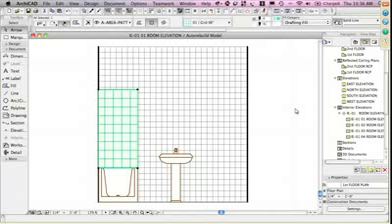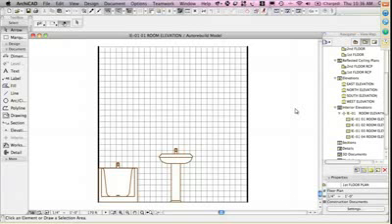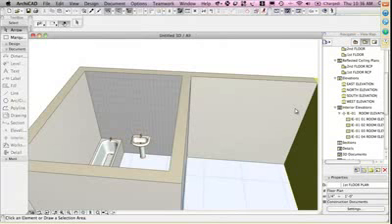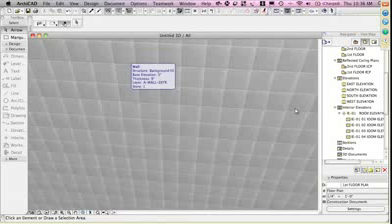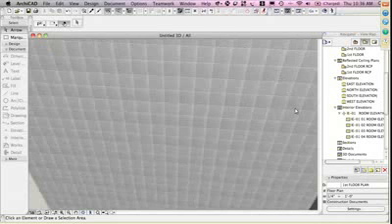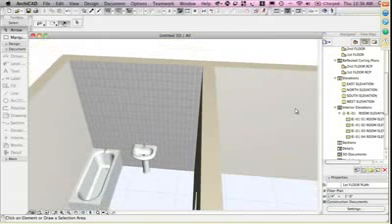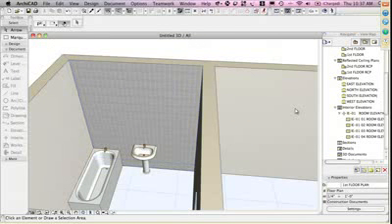So you can do some combinations like this, and this shows up automatically as long as you have vectorial hatching turned on. If I go to the 3D view, we can see that there is a tile pattern. If we zoom in on it close enough, you can see it really sort of looks like tiles. Okay, so how can you do it just in a selected area? Well, probably what you need to do is to create a little thin wall that would have the tiles on it just in the area you want, which is pretty much how the thing is built.